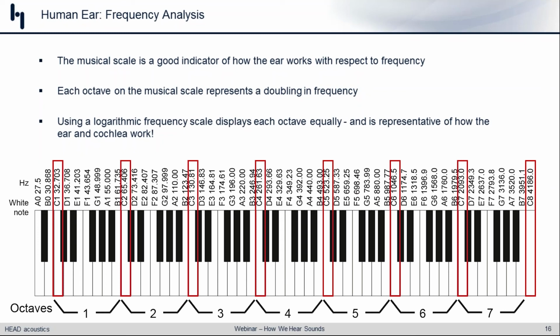Now, additionally, or maybe in tandem to that, part of the reason why we use a logarithmic frequency scale or axis typically is because of the way human hearing works, and that it is not linear. And you can easily tell here from the way 1 octave is spaced down at the lower end with about 30 hertz of separation, whereas at the higher end, you're talking 2 or 3 kilohertz in what separates 1 octave. And again, our hearing, our sensitivity of our hearing is similar. And we'll touch on that next week when we talk about octaves versus FFTs and how to analyze data.